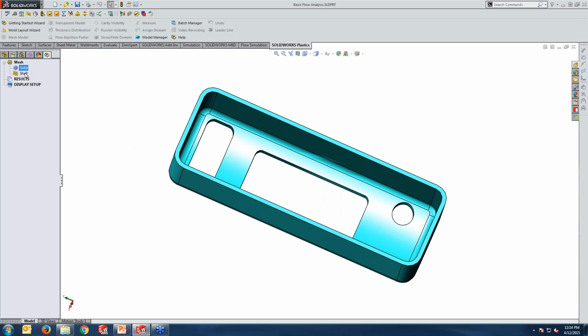So we have two types of mesh, solid or shell. Solid elements are basically the elements which are three-dimensional, meaning they can go over the thickness, length and width and height and everywhere else, while the shell elements are basically 2D elements, meaning it's just a triangle sitting on one face and representing the face. For most plastic parts, we already know the thickness compared to the other directions is not that significant. Therefore, there is a valid assumption, and there is not much sacrifice in the accuracy of your prediction if you're using shell elements. But in specific cases, that could be different.